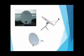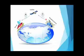The advantage of using the Ku band is that the receiving antennas may be smaller for a given amount of gain. The biggest problem is the increased attenuation of the downlink signal caused by rain. Any type of weather involving rain or water vapor can seriously reduce the received signal because the wavelength of Ku band signals is near that of water vapor. Therefore, the water vapor absorbs the signal. The digital signal is transmitted from the satellite to the receiver using circular polarization.